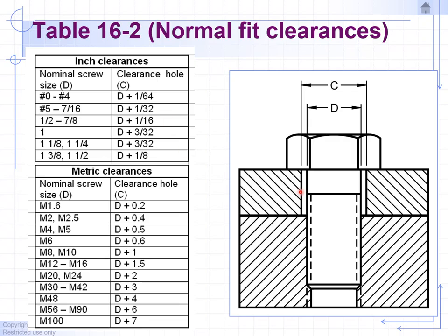Okay, so if you're dealing with a quarter, or 0.25 diameter bolt, add 0.03, and so you'll have a clearance hole of 0.28. And for metric, we're going to use these for our clearances. So these are the charts that you're going to follow. Typically, I'll go with 0.03 and maybe 0.06 for my clearances, depending on the size of the bolt.